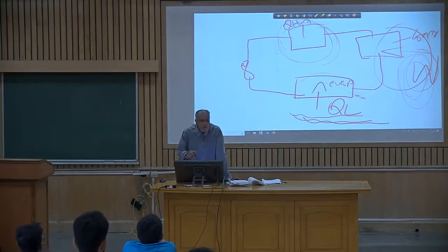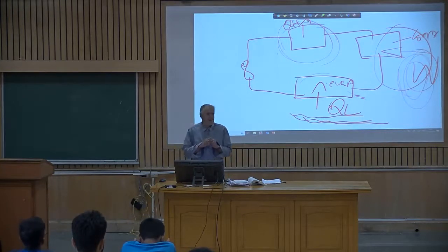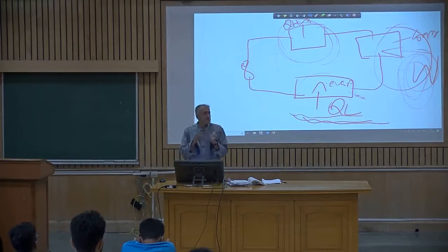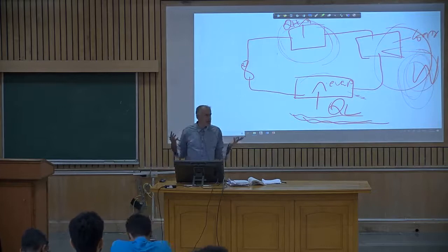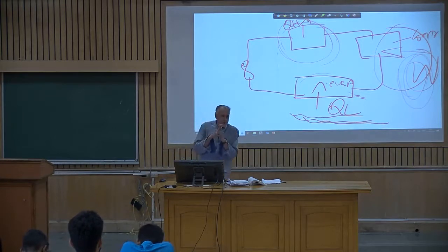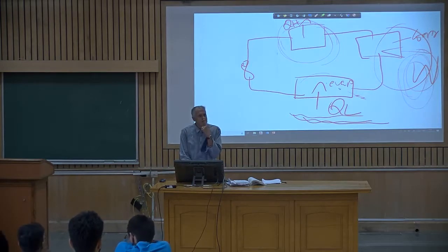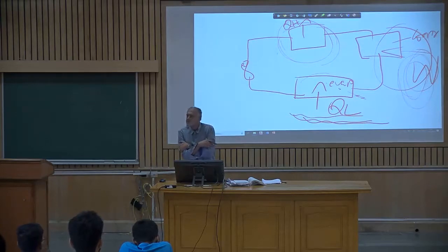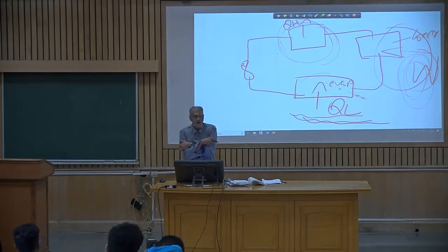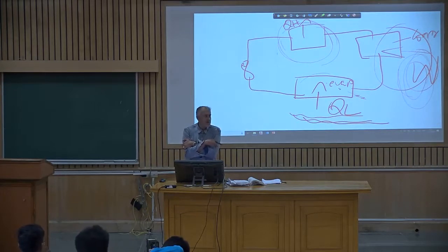That is why if this QH did not happen, the process won't happen. Yes? The process will not happen. If QH is not rejected back and the entropy of the surroundings does not increase, the process will not happen. Because here in the refrigerated space, when you suck the heat in, what happened to the entropy? Of the refrigerated space, what happened? Entropy decreased. Of the material, what happened? Entropy increased because the liquid became vapor.